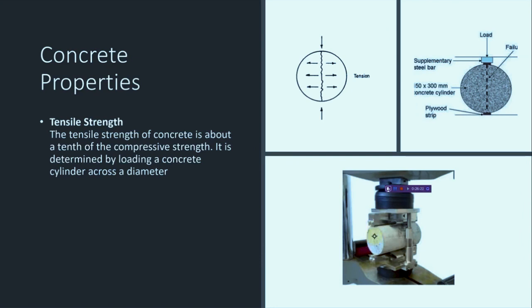What you look at here in this picture, you see that this is a concrete cylinder. So this concrete cylinder is not put like this, it doesn't stand upright. Okay, it will be lying, how do we call it, lying down, not vertically but horizontally. So we treat this like a beam. Normally the force is placed from above.